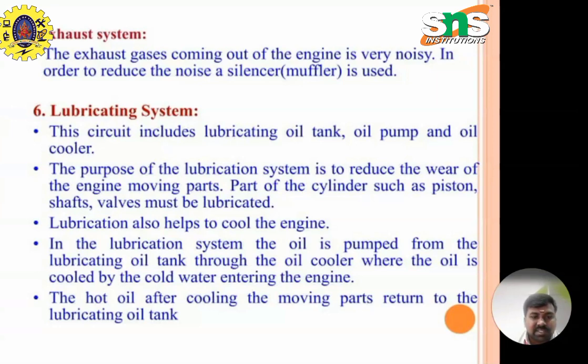The lubricating system. This circuit includes the lubricating oil tank, oil pump and the oil cooler. The purpose of the lubrication system is to reduce the wear of the engine moving parts. Parts of the cylinder such as the piston, shaft and valves must be lubricated. Lubrication also helps to cool the engine. In the lubrication system, the oil is pumped from the lubricating oil tank through an oil cooler, where the oil is cooled by cold water entering the engine. The hot oil, after cooling the moving parts, returns to the lubricating oil tank.